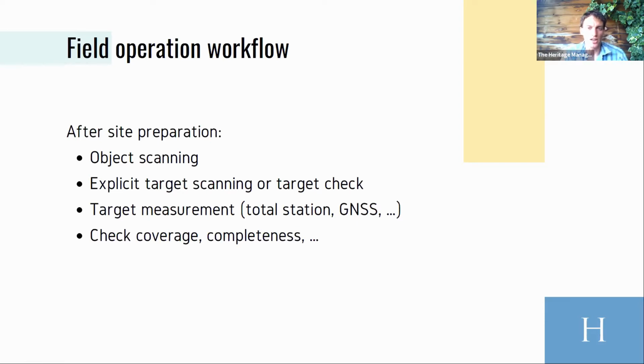And then afterwards, I can point my laser scanner in the direction of my first target, my second target, my third target, etc. And these targets are then measured at the highest accuracy. And the interesting thing here is that most scanners will automatically detect the centers of the targets itself. So actually, the coordinates of your targets are automatically incorporated in the point cloud itself. And that's a very useful property that you can use for the point cloud registration.